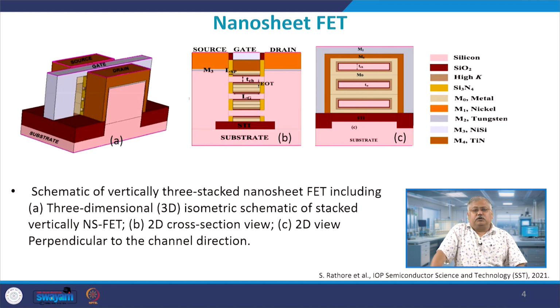It was also referred to as a quasi planar device. Why? Because rather than having everything on the same plane, the gate was slightly raised with respect to source and drain, right. That added a third dimension to the overall width of the device, thereby giving the designer one more knob to play with while optimizing it, but it also added some extra fabrication steps in order to design such a FinFET with accuracy and with stability.